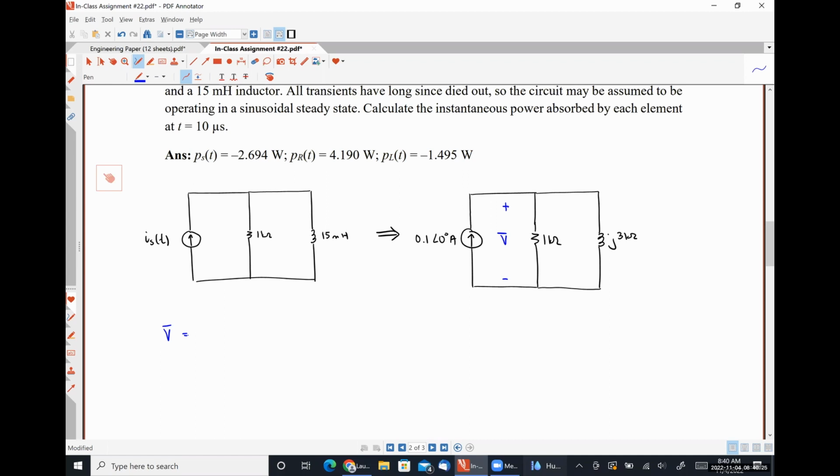Thank you, Zachary. We have a current source in parallel with two impedances in parallel. So just I times ZEQ gives us what we're looking for. Why make it any harder than that? Thank you for the correct suggestion.